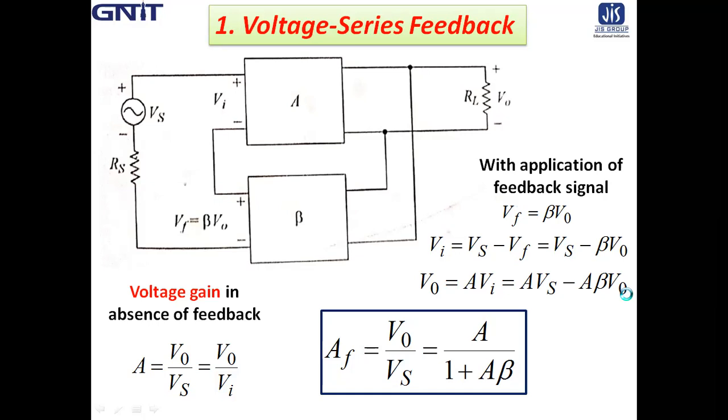Now we know that the overall gain with feedback, AF, called the closed loop gain, is the ratio of V0 by Vs, which is A by 1 plus A beta. Therefore, the voltage gain reduces by a factor of 1 plus A beta.